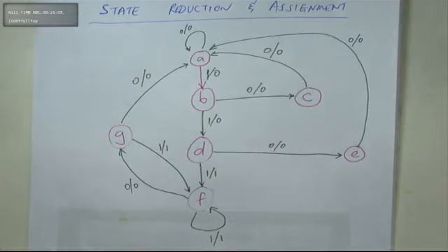Okay, so how many states in our machine? Well, first definition, is this a finite state machine? Yes, because it has got a limited number of states. A, B, C, D, E, F, G, 1, 2, 3, 4, 5, 6, 7, right? Is that correct? 7 states. Now, if there are 7 states, how many flip-flops do you think are in use? 3 flip-flops. 3 flip-flops should be able to accommodate 7 states, right? So, in terms of bits, how many bit system is this? It's a 3-bit system, right? 3-bit system, 7 states, that means 3 flip-flops.